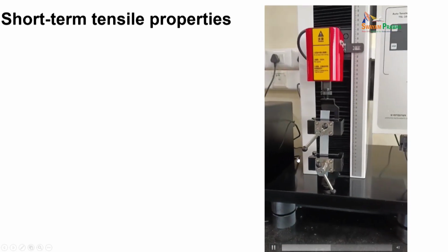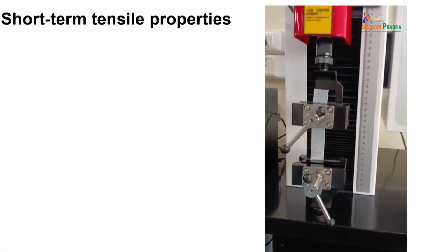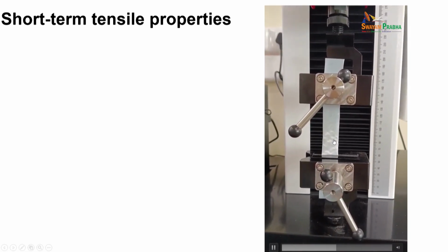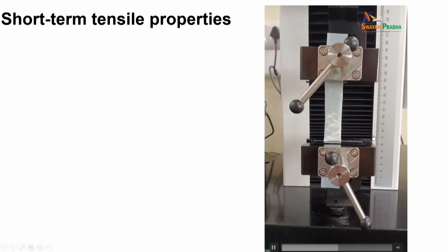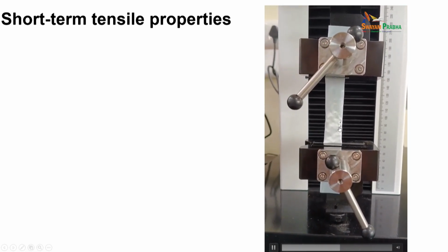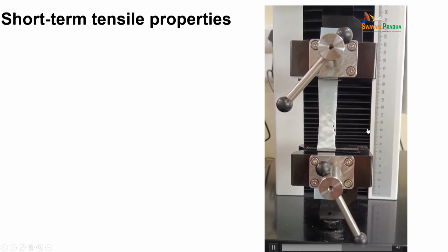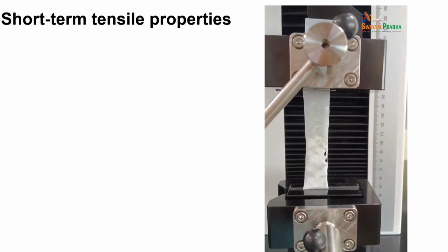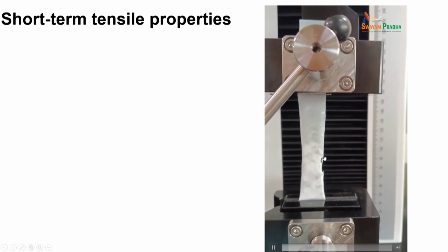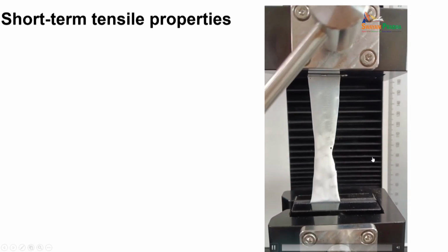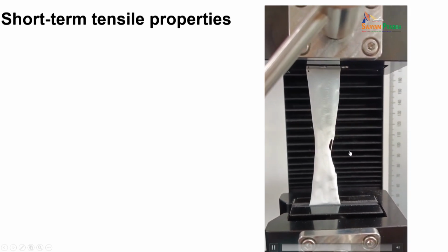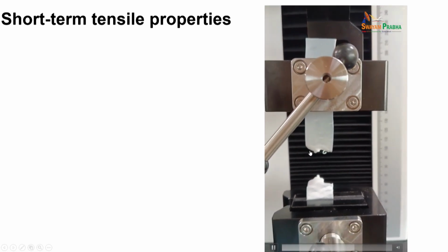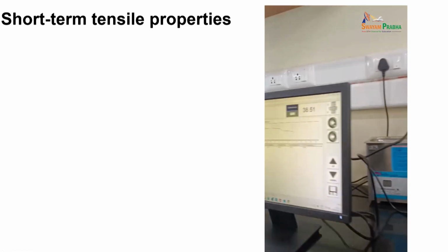So I think he's going to look at what happens to this film as the top portion moves upward. You can see that some features are coming up, some whitish marking comes up. You can see some holes getting formed as you pull. And this hole becomes larger and larger, and you see there is a fracture here, more fractures. All the while the top one keeps moving. Then there is a rupture. The film basically breaks after you apply a sufficient amount of load, okay.